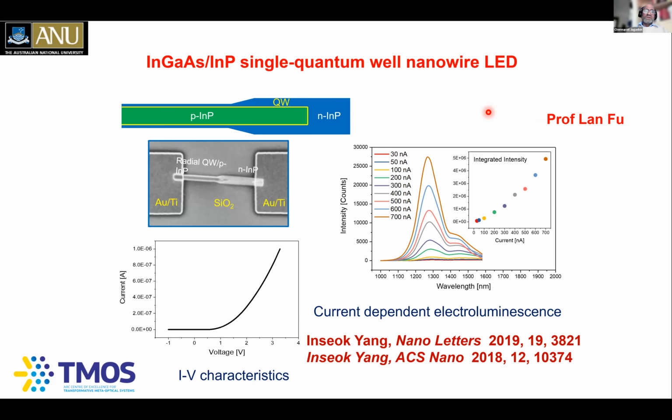It turns out that when you put these metals, you've got a very high absorption, and they create a very lossy cavity. Because of the lossy cavity, you pump them harder, you generate more heat. That means the gain peak comes down and you have to pump them harder, and it becomes like a vicious cycle. So now Nikita Gagrani, who came from IIT Kharagpur, is working on trying to get over this by replacing these metals with transparent conducting oxides like indium tin oxide, zinc oxide and tin oxide, and seeing whether we can really get over this problem and make electrically injected nanowire lasers.